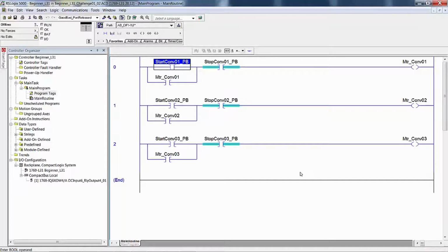If you're working with a new tag, do not open the properties on an existing tag. Just type it in, then right-click, new, change whatever, and create. Now, once you become confident in what you're doing, you can double-click on the tag name, edit the characters, press enter. Right-click on the undefined tag name, select new, and after making sure the tag scope is correct on the first line, then select create. This can be done in seconds, but only if you are confident in what you are doing.